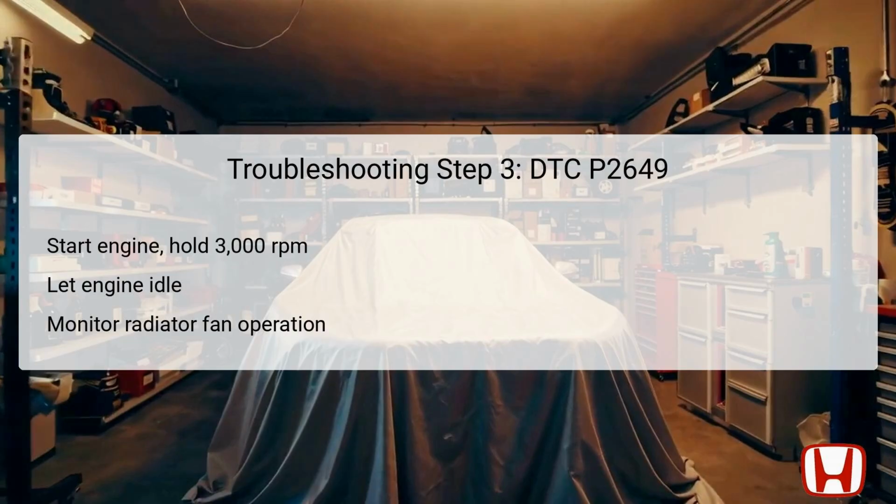It is essential to keep an eye on the operation of the radiator fan during this period. The fan is designed to activate at a predefined temperature to prevent overheating. Once the radiator fan comes on, the technician can let the engine idle, returning to a normal operating condition. At this stage, it's important to observe any unusual behaviors or sounds from the engine.